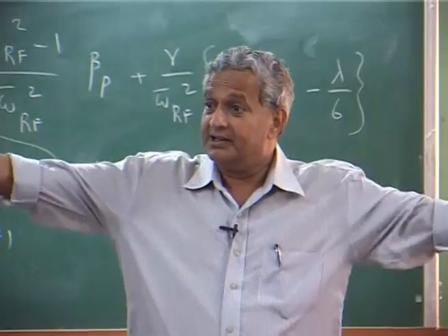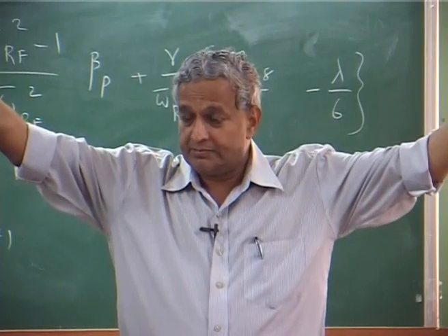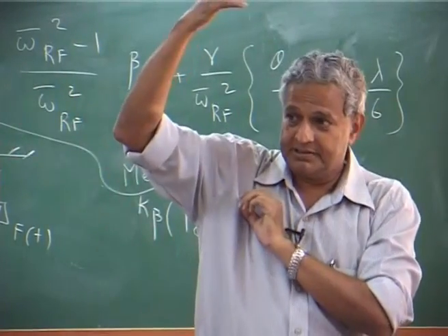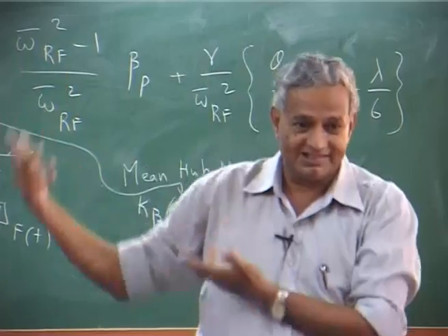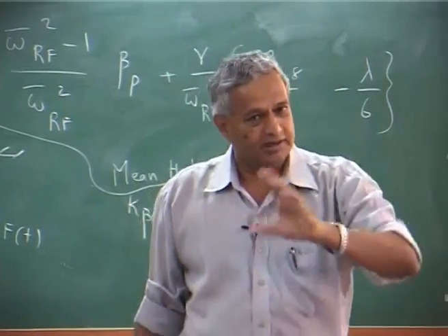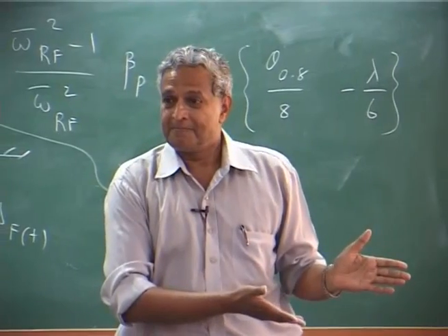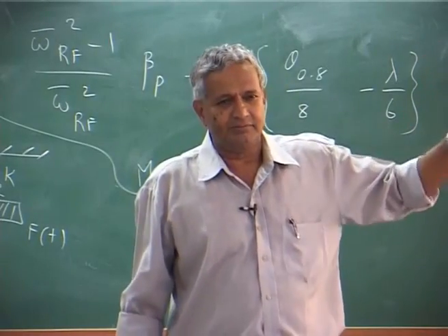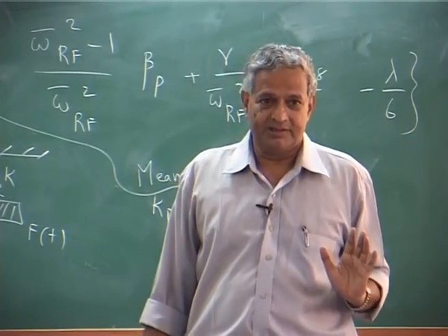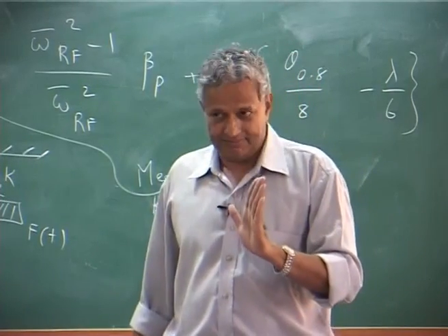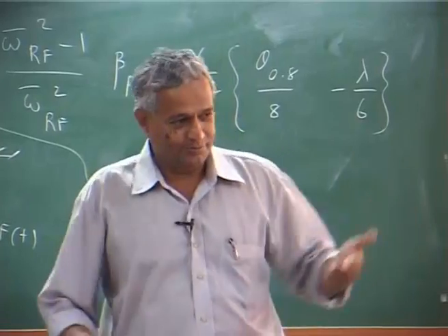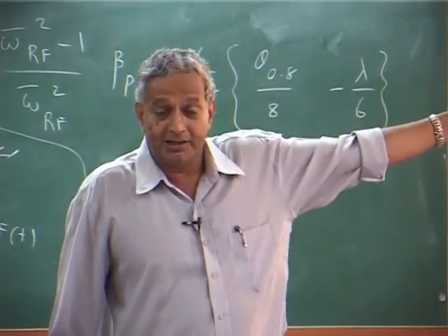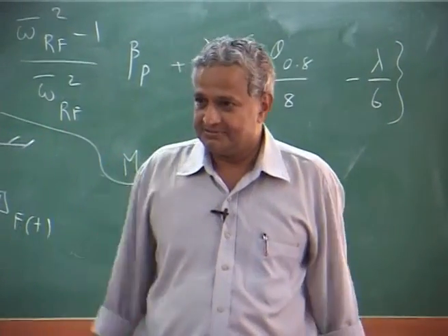Okay. Because if the coning is too much, that means your lift is very large, that is why it is going up. If the coning is very less, means my lift is less. Okay. So, the coning angle changes with your weight condition. That is why all these are just to give some 2 degrees, you relieve the hub moment. It is purely from a structural design point of view. Okay. Of course, aeroelastically it will have an effect. That part will come, I hope we will be able to do it, or otherwise we will forget about that aeroelastic effect of beta p on the blade, some stability, etc.